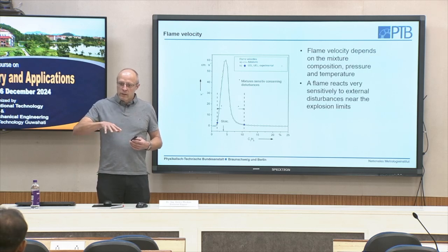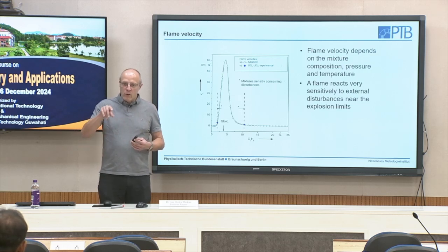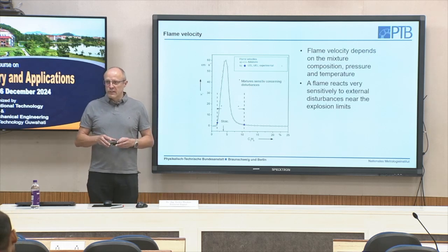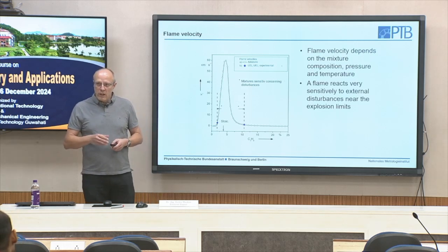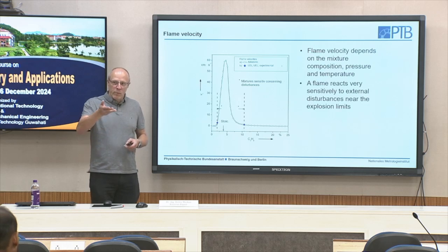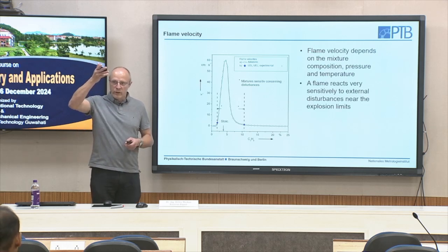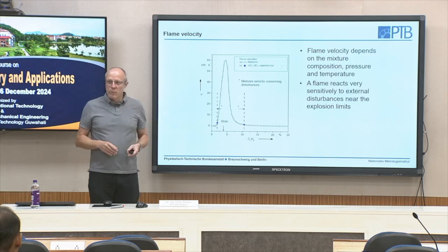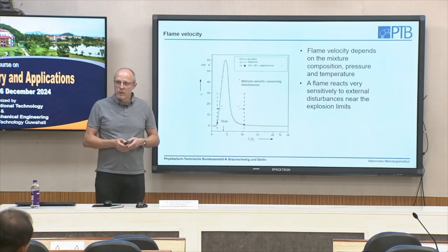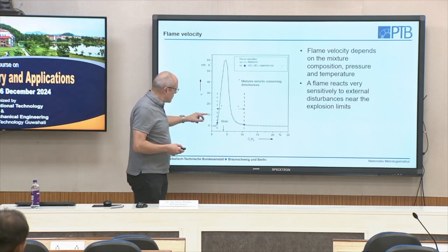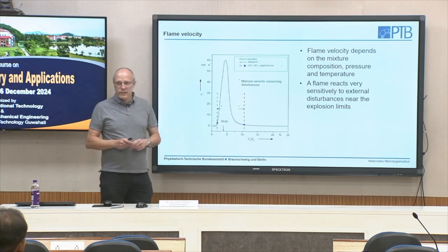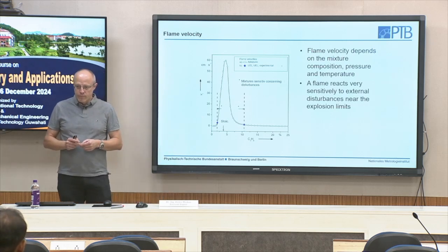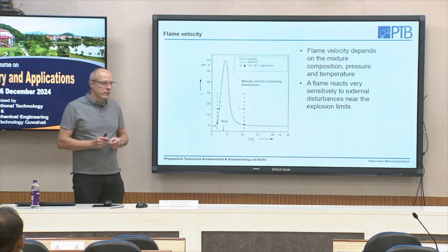and then you create a core of hot gas, and then we have something like buoyancy. The flame is propagating upwards due to buoyancy and tries to burn the unburned mixture. However, below 10 centimeters, buoyancy is very important for flame propagation.